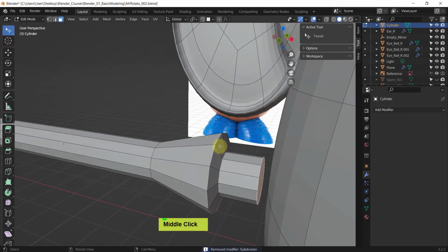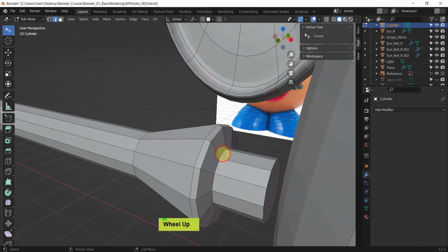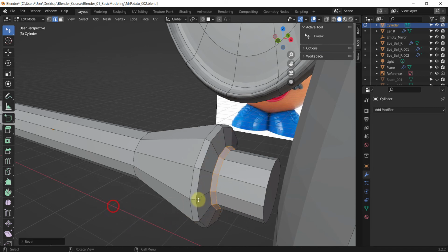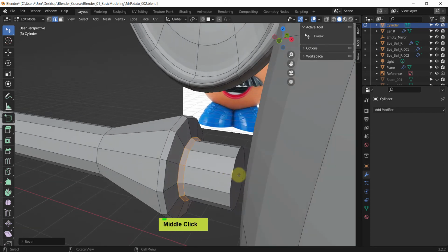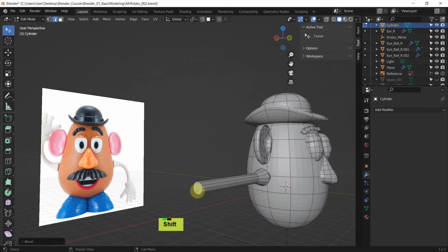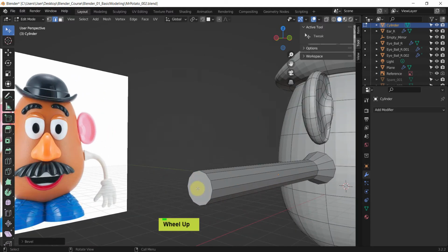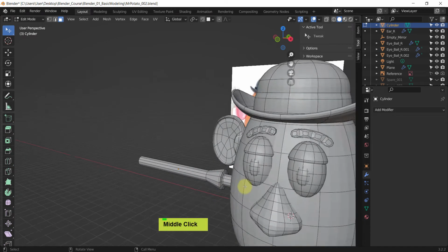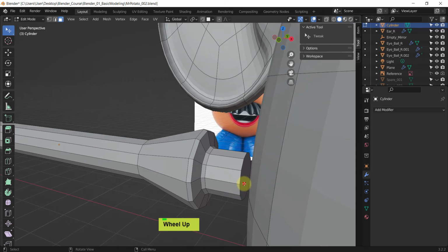I will do an edge bevel. So we are on edge level, select the edge and Ctrl B and use the bevel function, which was great. And also if you want to make this area sharp, we should do the same. So Control B, and yeah, where we are now in this direction. It's going well. Okay, great. And because if you remember, these polygons could be a little bit tricky, I will just select this polygon and simply delete this one. So it will be kind of a simple tube, and also delete this one.